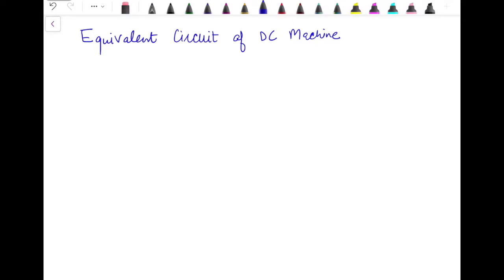The field winding is always supplied from a DC source, while the armature, depending upon whether it's a motor or generator, may be supplied, or we may collect the output from it. The field winding is placed next to the armature, where the armature is represented by a circle showing the generator or motor rotor, surrounded by two brushes.